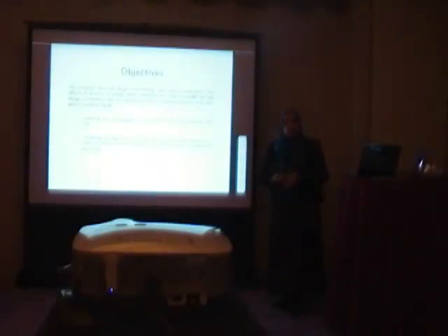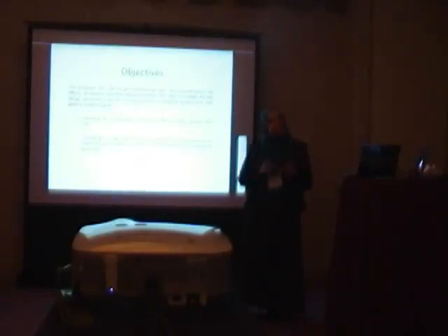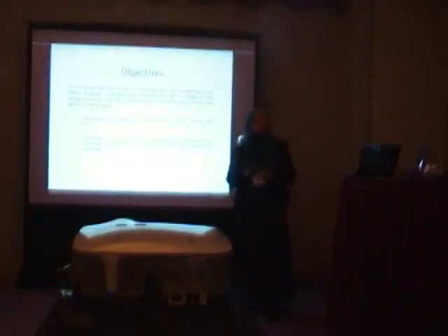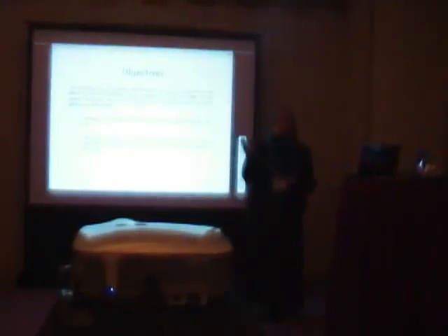Before I go to the objective, I will talk about variability-tolerant NoC link. By variability I mean process variability. CMOS fabrication processes are mainly front-end and back-end. The front-end processes are those involved in the fabrication of the device. The back-end are those involved in the fabrication of the interconnect. As technology scales down, the fabrication process makes components not as we designed. There is variability. This variability will change the electrical components of the devices and the interconnect, and in consequence will affect the delay.